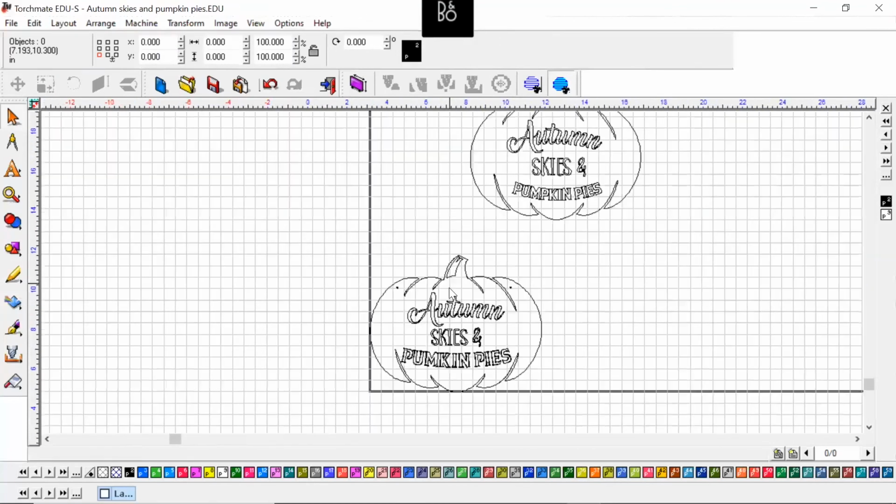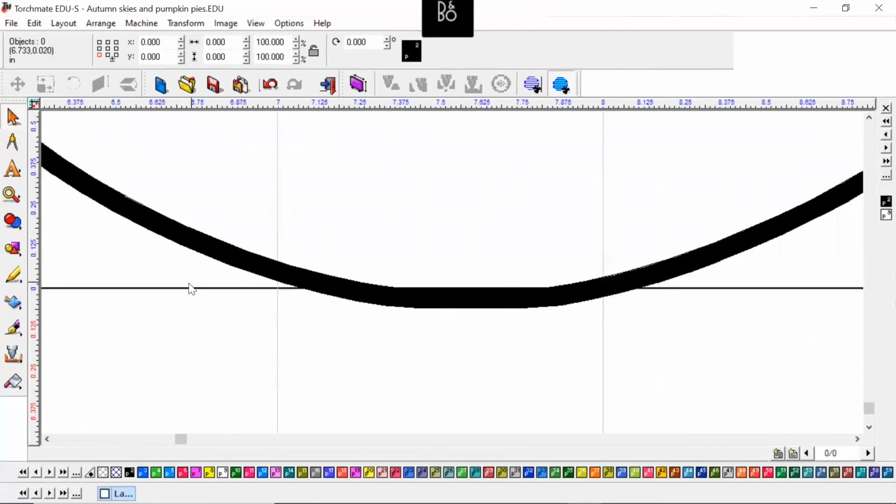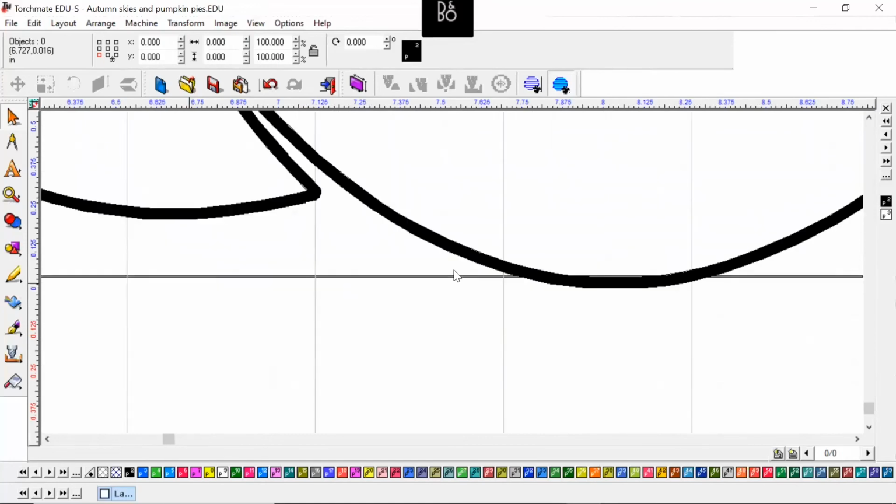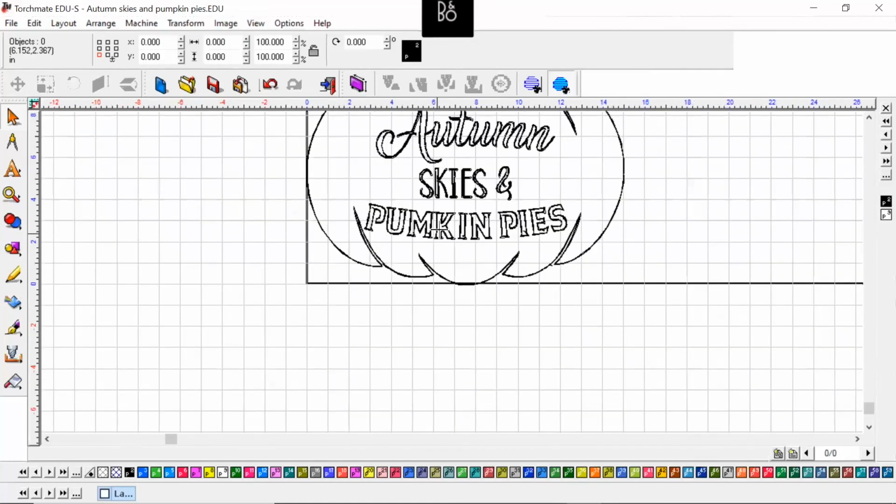This one looks okay. Like I mentioned before, we've got to make sure that every job we finish before we save it needs to be up against this edge. And when I show you on the actual machine, if we don't save this where that line is on the inside of this line, it's not going to detect it when we go to transfer it into G-code.